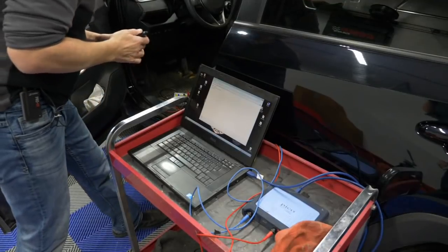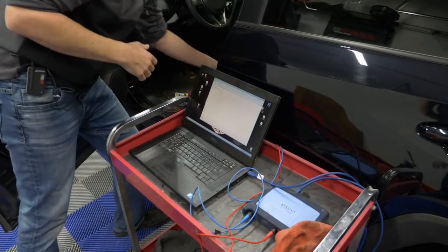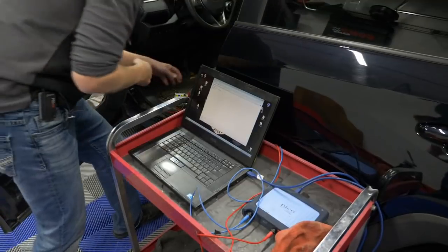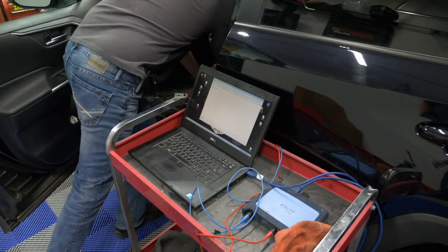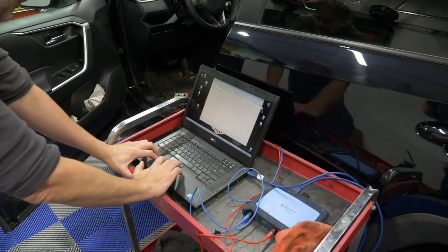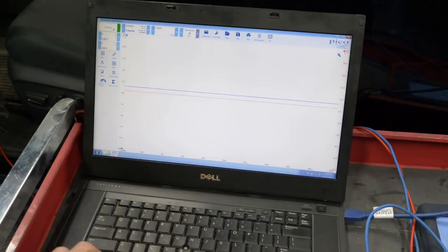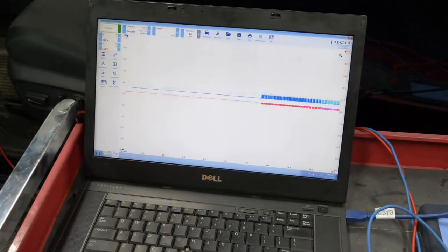With this being a kind of an advanced CAN, my guess is just having the door open, it's going to send messages, but I'm not sure. What I'm going to do is just turn key on, engine off, and that should send plenty of signals for us.